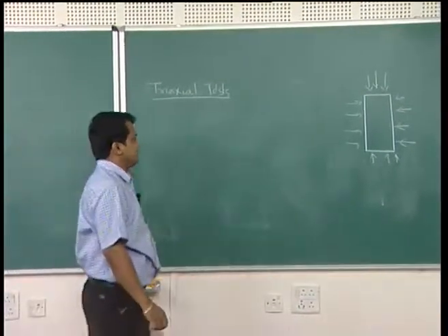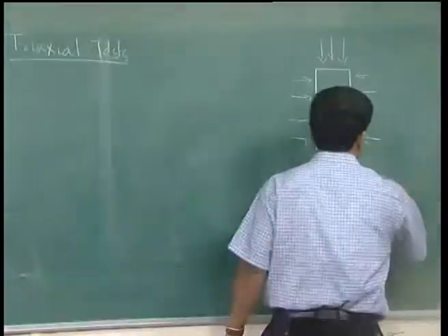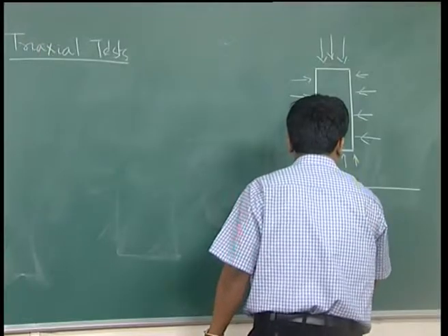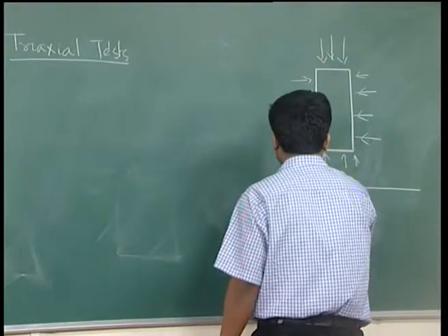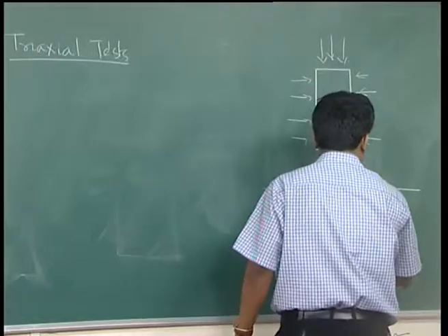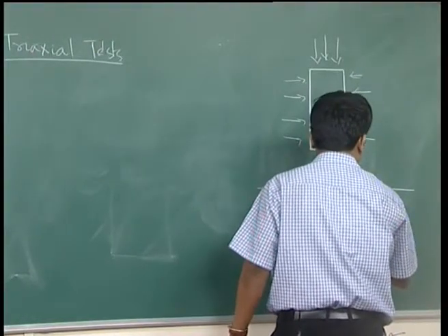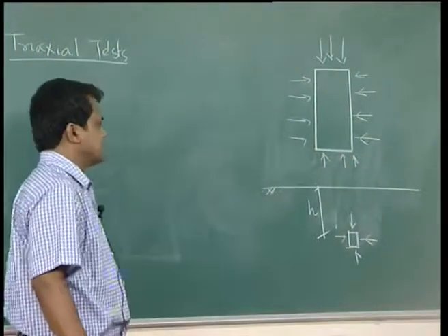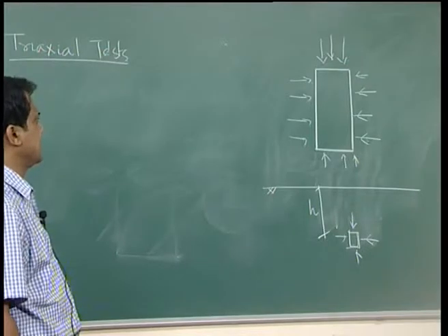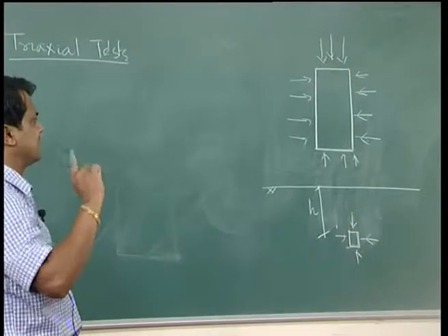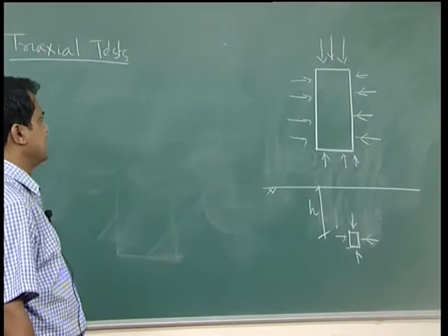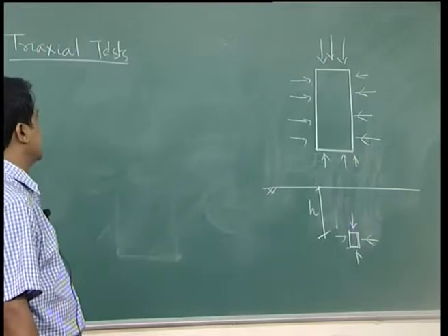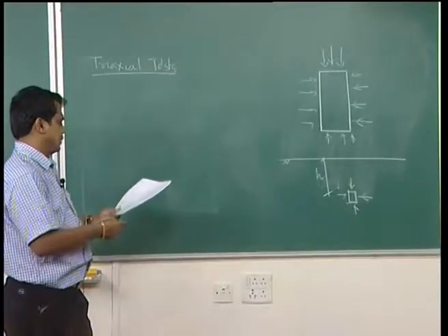That means it will truly simulate the soil sample when you take it at any depth below the ground surface. This soil sample has vertical as well as lateral stress. To simulate the soil sample below the ground surface, stresses in the vertical, lateral, or all around x, y, z directions have to be applied to simulate exactly these field conditions, and this triaxial test has to be performed.